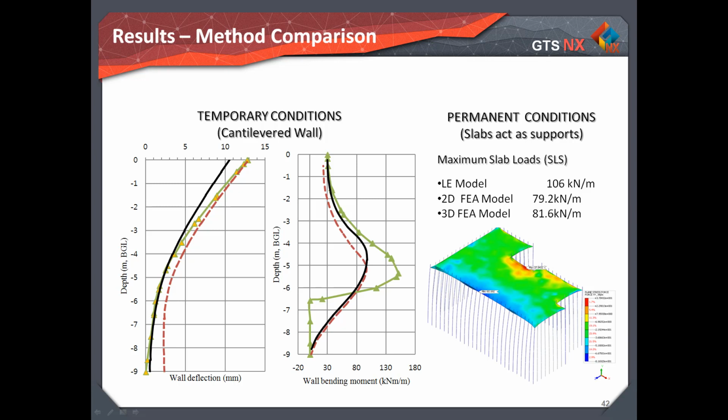It can be argued that the live loads from columns or the surcharge on the active side are for design purpose and can vary significantly in practice. By removing the surcharge and the moment load, the maximum pile deflections reduced to 6 millimeter in the 3D model, which is even closer to what was observed on site, 4 millimeter.